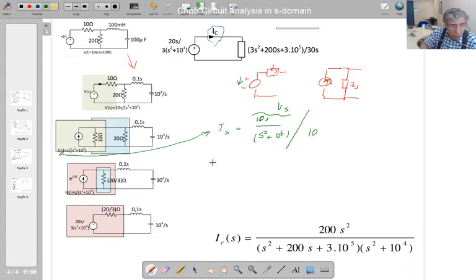So that is going to be 20 times 10 over 20 plus 10. So that is the equivalent resistor value. So an independent current source is connected with a resistor. So that pink area, if you apply the source transformation once more, transfer this independent current source to an independent voltage source.